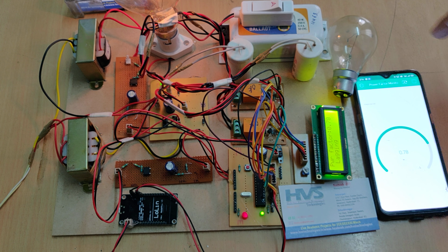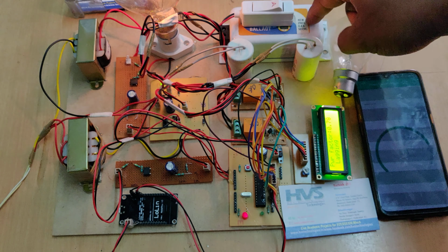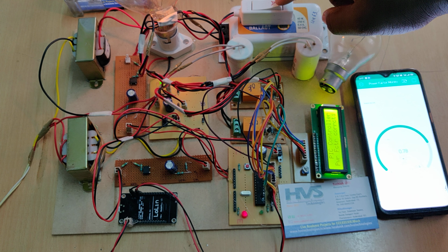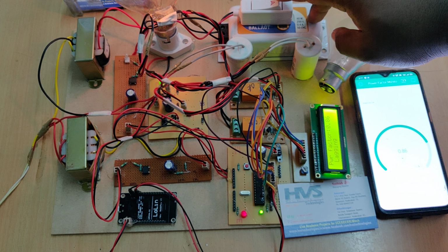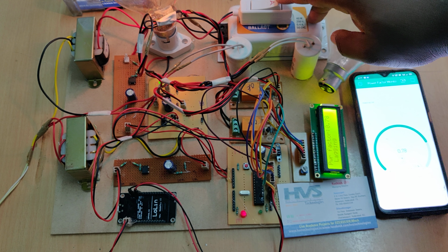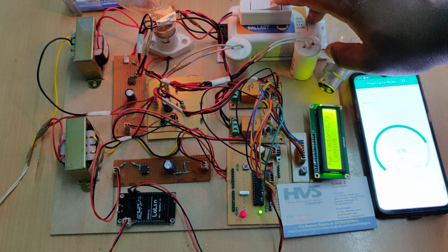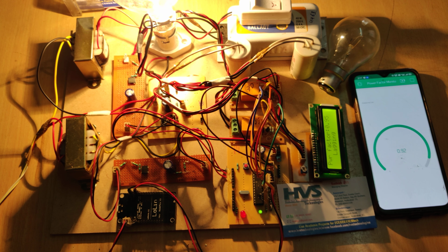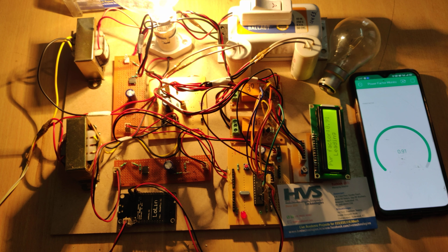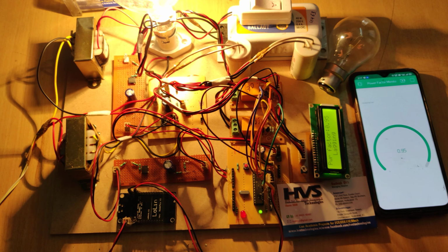And whenever I switch on this inductor, because the inductor is connected in series with the R load, that's why it is dimming, because the voltage gets divided between these two. Now if I switch off this switch, the inductor will isolate from the R load, and then automatically the power factor will come to leading. Right, it is leading now, and now the microcontroller will isolate the capacitors from the load directly. We can demonstrate the same with this.